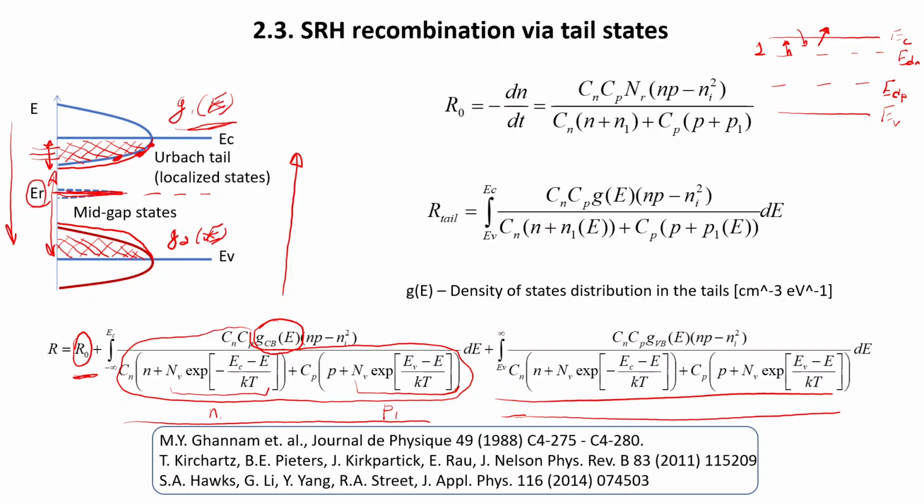I think no, but can I proceed with the question? So you are right, it's not, because if we have a shallow energy level within the first region, it will act as an efficient trap center, but will not participate efficiently in recombination. Why?